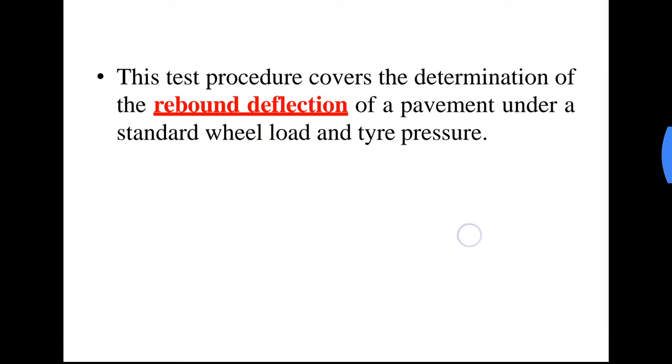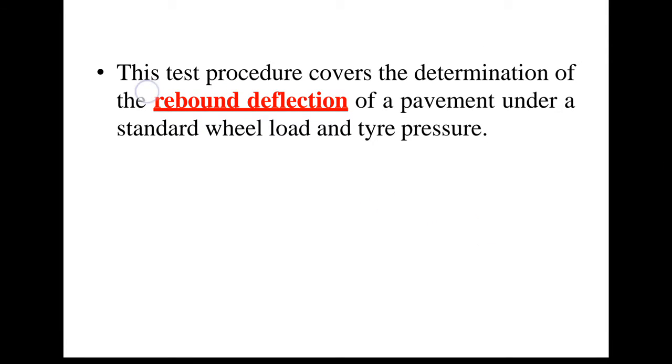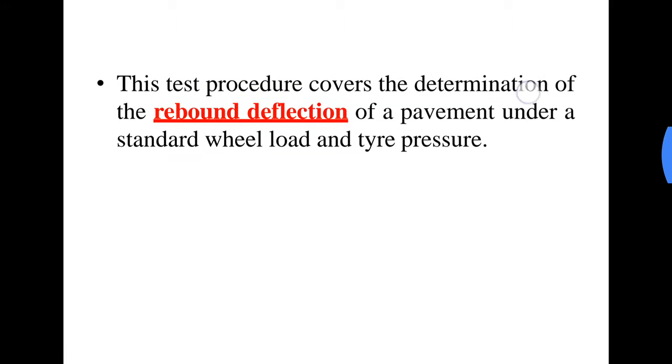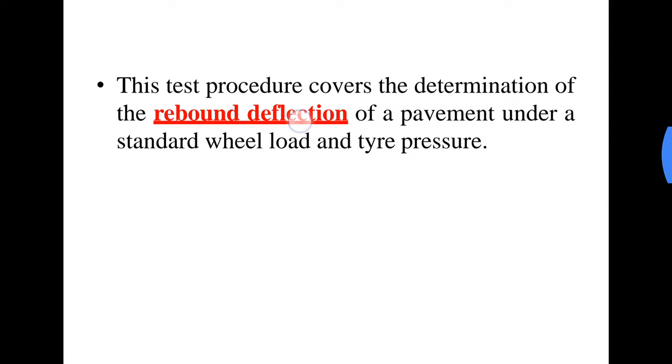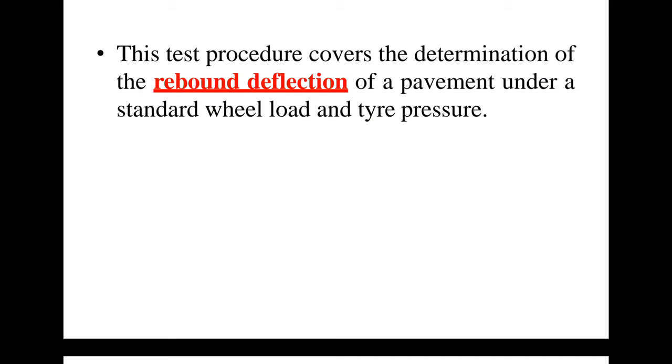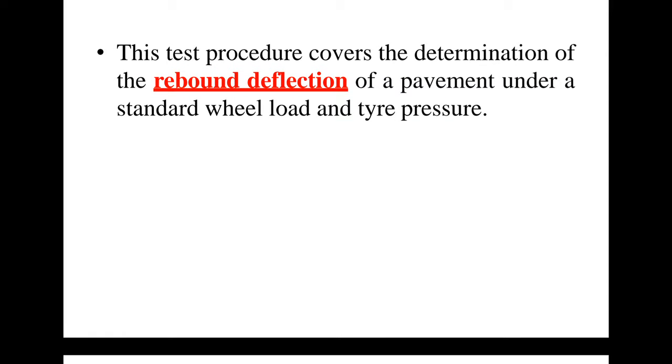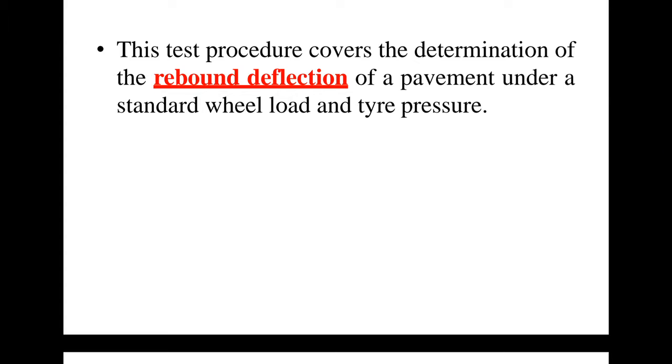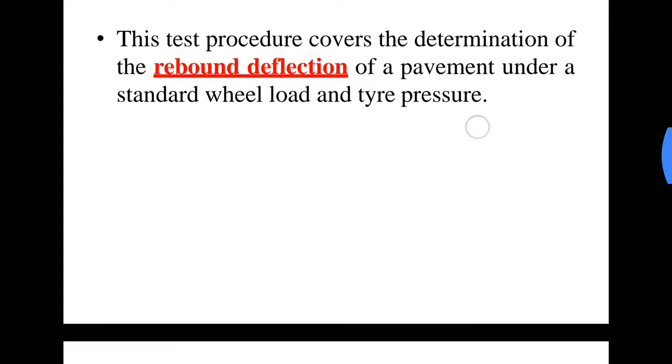Now these BBD studies, their test procedure covers the determination of rebound deflection of pavement under a standard wheel load and tire pressure. So in BBD studies or Benkelman beam deflection studies, what we are trying to do is measure the rebound deflection of the pavement. Okay, once you apply a load, then you take out that load, then how much is the deflection, that is what we are trying to find out under standard wheel load and tire pressure.